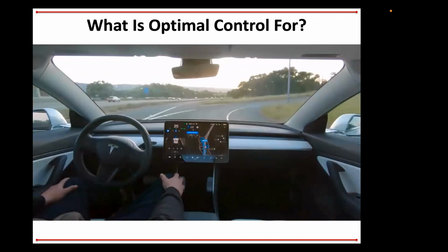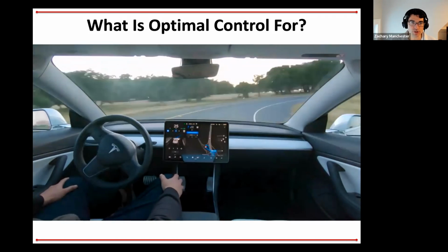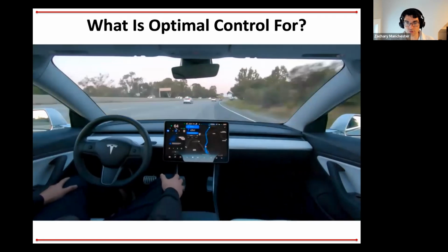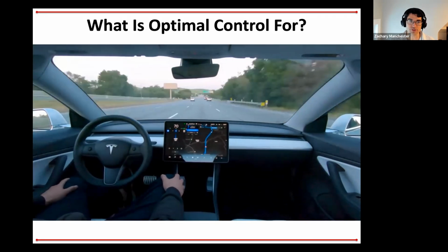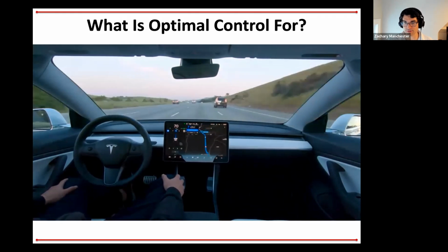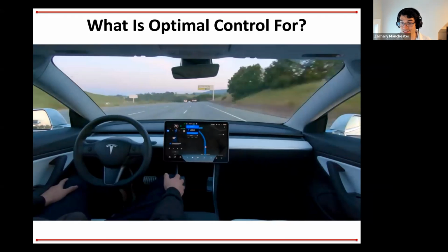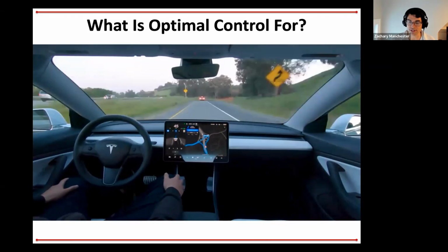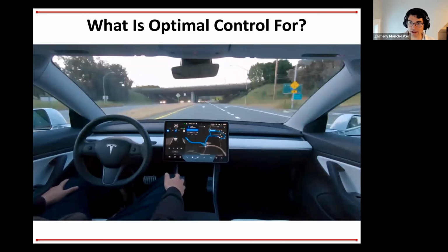Should be an adaptive controller. So this stuff, not so much actually. The standard approach here is again MPC for a lot of it, and then often some lower level linear tracking control stuff. Here the standard approach is to use a simplified dynamics model for the car. A lot of times people use what are called single track or bicycle models. And then it's nonlinear MPC with constraints for collisions and obstacle avoidance and that kind of stuff is the standard way of doing this.